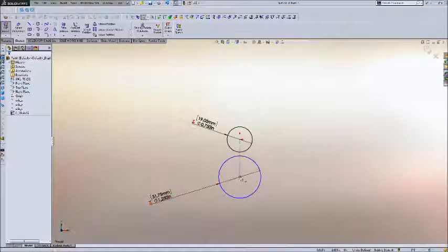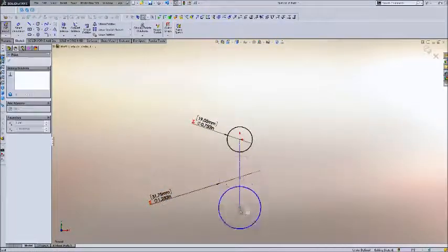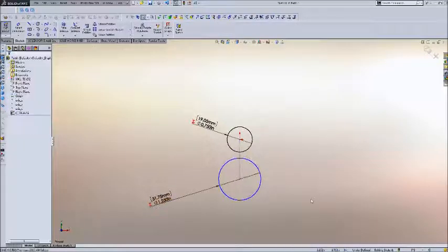You can see it's still blue. The sketch is blue because I haven't defined how far apart these gears are. Now, if I model the pitch diameter, the way I do that is just gear tooth count over diametrical pitch, and I don't need to add the extra 2.